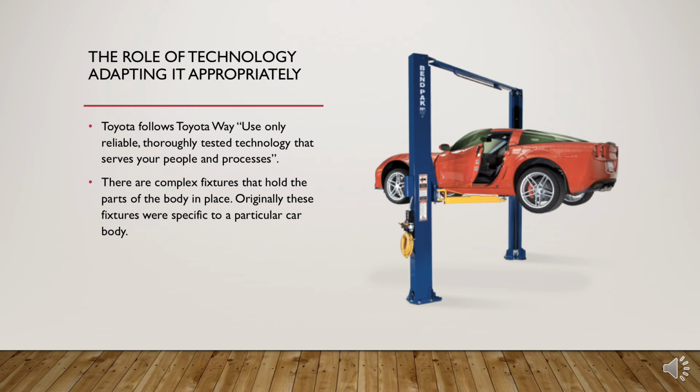So now, instead of the car body riding on a custom pallet, it is being held in place by robots that can be programmed for each car body. The bodies ride on something like a Skylift. The image showing on the right of your PPT is something like a Skylift. The earlier pallet system held the body together from the outside in and had fixtures sized and positioned differently for each vehicle.